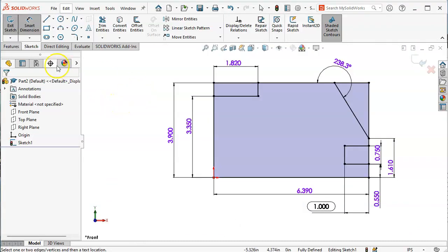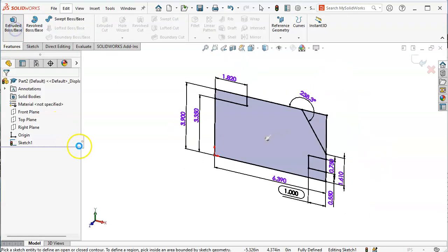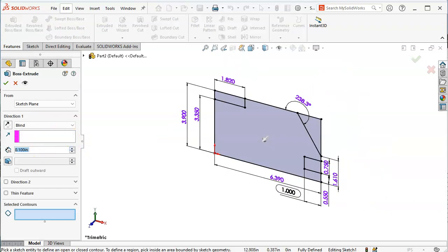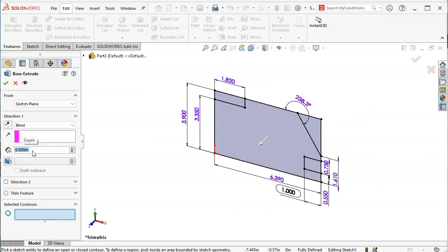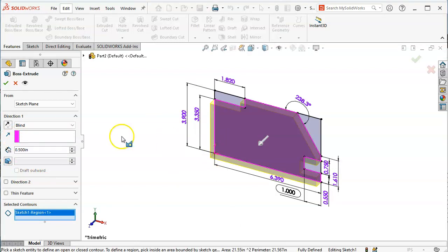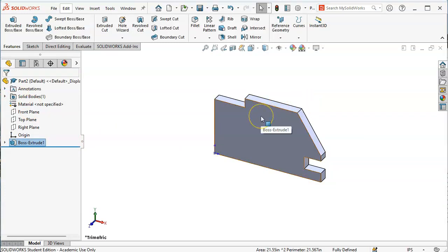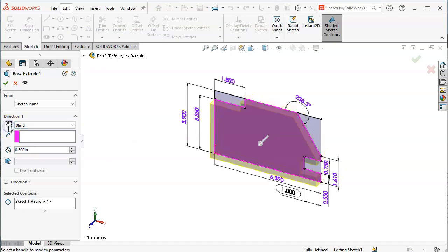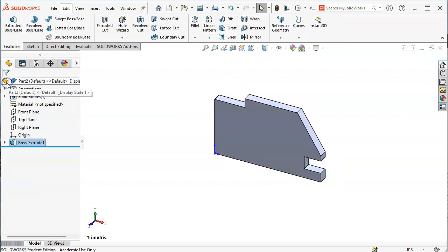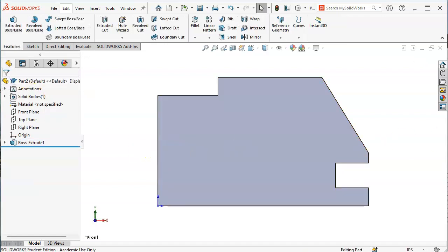We can use the contour and region, so kind of group those. Let's see, what was the thickness? 1/2 inch. So 0.5. Contour and region is the interior. This time I want it to go away from me, so I can reverse that direction. And again, getting back into it if I change my mind, it's not permanent. We just toggle, is it going in the Z away from us, negative possibly direction, or towards us in a positive direction.